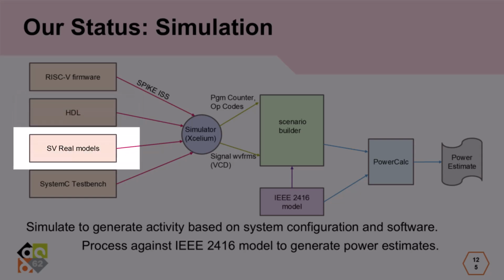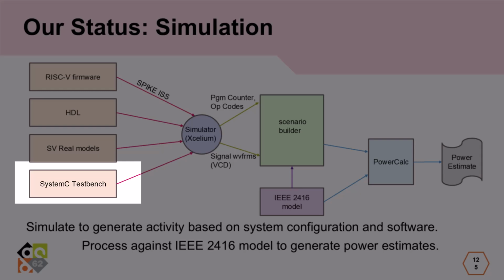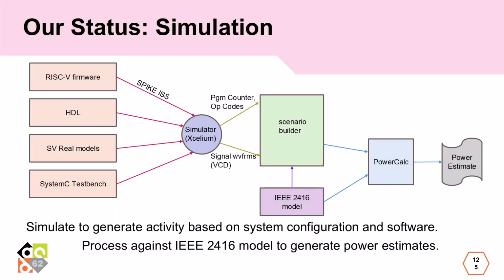We have SystemVerilog real models for the transceiver, the power management and the PLL, and some SystemC test bench elements to manage the transaction-level radio I/O as well as some other traffic. All of that is digested by the simulator. In this case, we're using Xcelium. And the simulator produces some signal waveforms in the form of VCD files and a set of program counter and opcodes from the instruction set simulator.